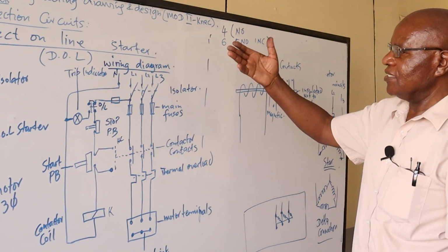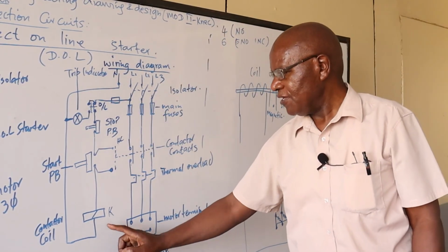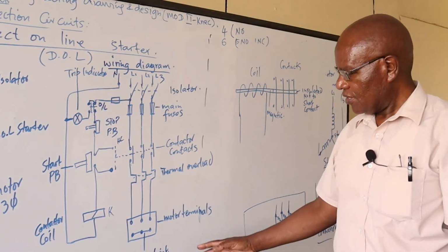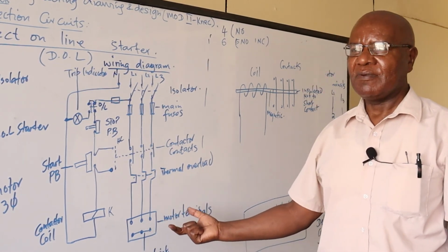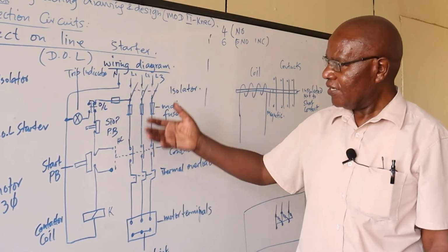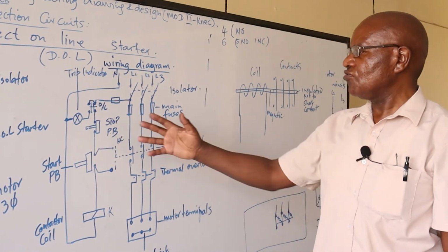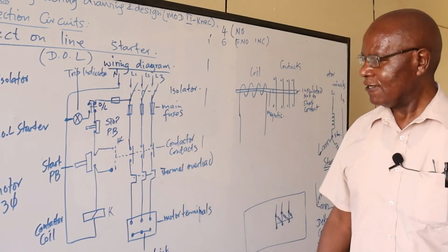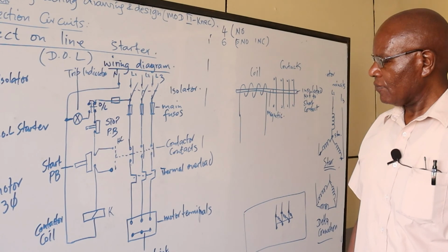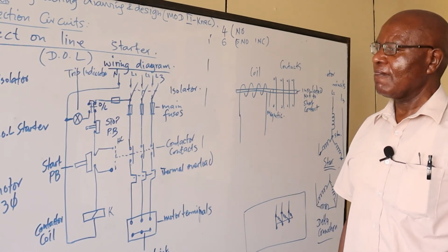The other one is, in case there is a lower voltage, it needs to be detected and the feed to your motor should be cut off. The windings of the motor can also heat up. Again, you detect the heat on the windings, and that sensor is connected to your control circuit to stop your motor. And that's all there is to the direct online starter.